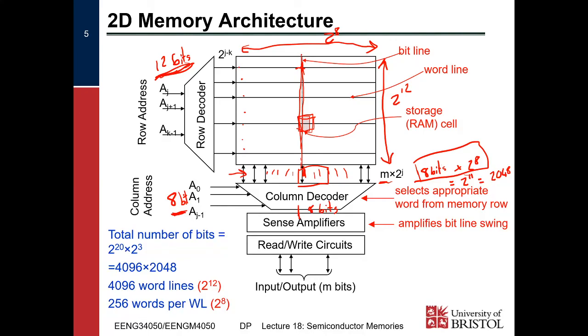Right. Okay. So we've got a 2D memory architecture, and that works fine. And then we get up to multiple gigabytes of RAM, where we've got greater than 32-bit addresses, or sometimes even with just 32-bit addresses if you want fast memory. You realize, hang on, wait a sec, we've now got a very, very large row or column address. That's not going to work. We've got at least like 18 bits here and maybe 14 bits here. It's really getting too big for us again.